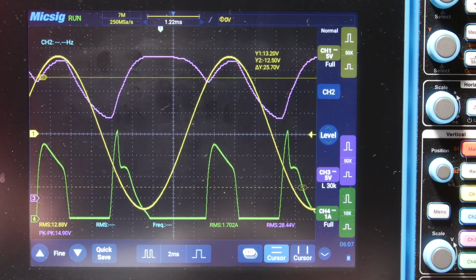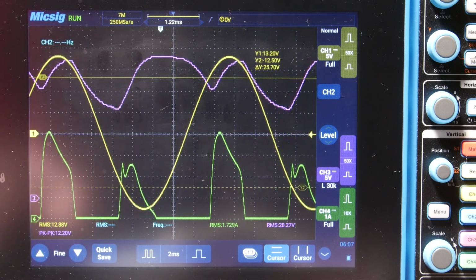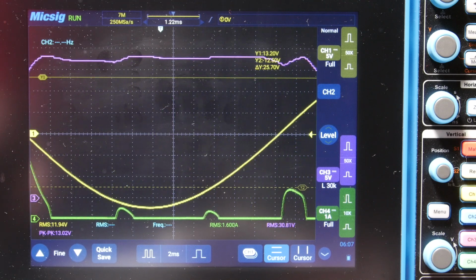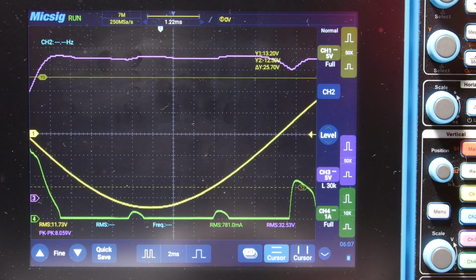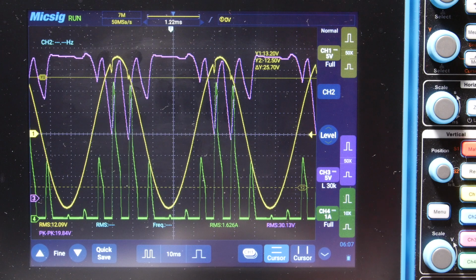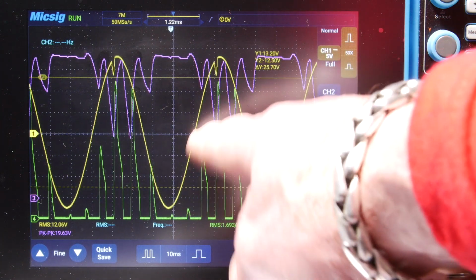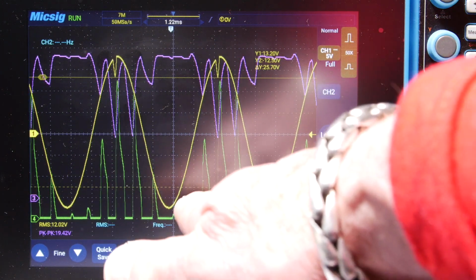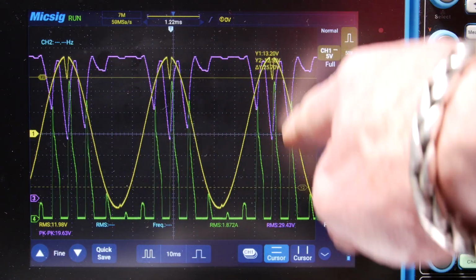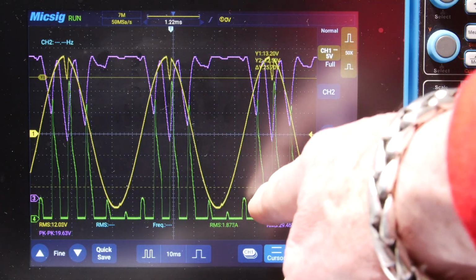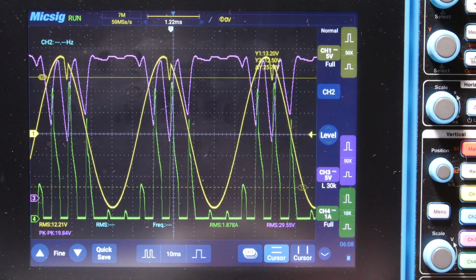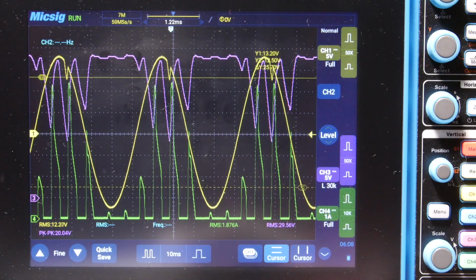Okay, I'm going to go a little bit lower in frequency even. Let's go 20 hertz. Okay, there's our 20 hertz. Okay, there we go. Look at that. Look what it does. Because we got 120 hertz basically coming in charge, right? Whenever we get a pulse, that is where we're getting a big old, let's say a bass note, then we get a bunch of charge cycles. And in between, not very much. So I thought you might find that interesting.